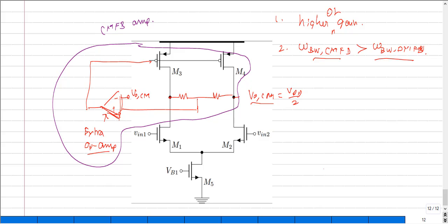So how does this requirement pose a constraint to my entire design? Let us assume that the common mode feedback amplifier were slow, like the entire bandwidth of this circuit is very small, and its basic function is only to provide a kind of DC biasing around this loop. Whenever there is a sudden spike across any supply line, there will be a shift in the value of VOCM, a shift in the common mode voltage by a larger quantity.